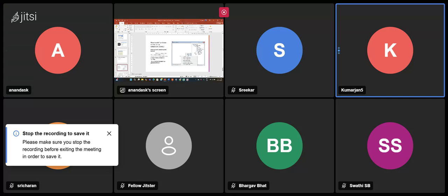Yeah, you can see it. It is an individual one. So you're talking about the cell one. You try to log that cell one and send those messages. It will take some time to send the CAN through the IG block. It'll show you the cell voltage, what signal it is taking, how the signal is coming, what values it is getting. There are so many parameters for one particular cell. Those variables are interacted with the CAN DBC file, and with the CAN DBC file you are checking whether values are popping properly or not.